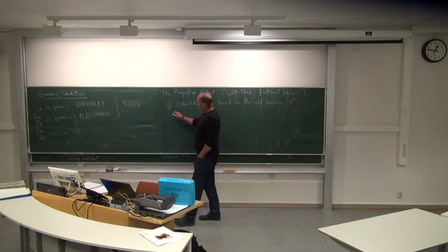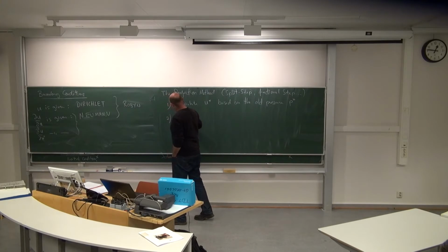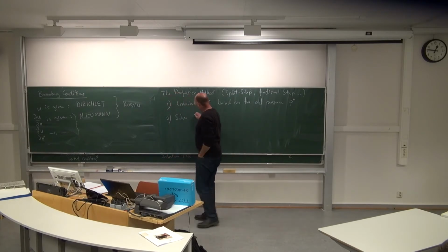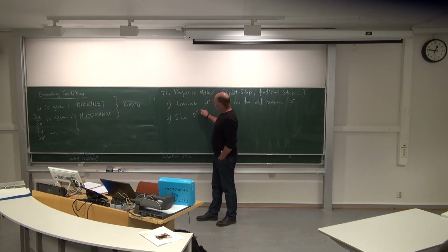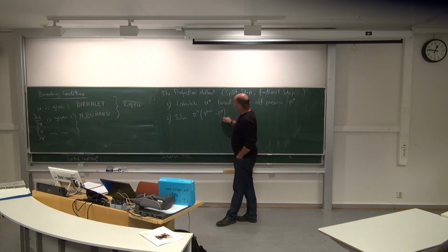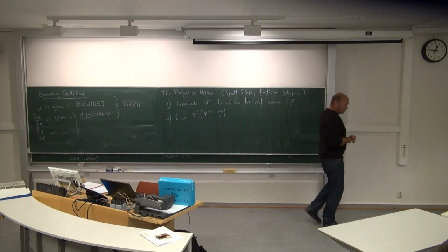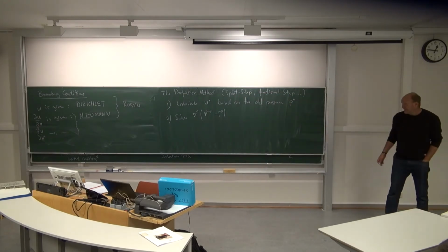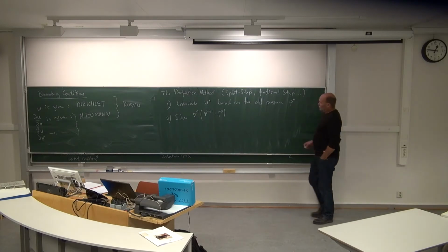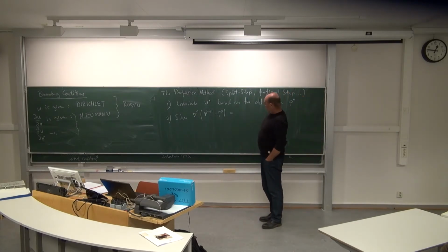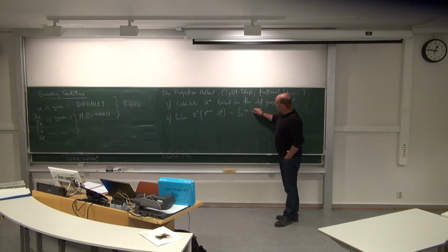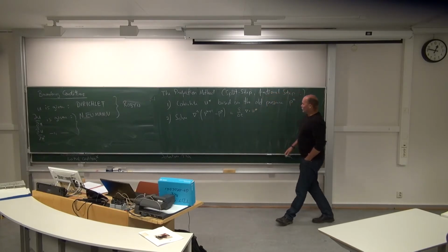Second step, that was a Poisson equation for the new pressure. Actually, the pressure difference between the new and the old pressure, and this one now should be equal to, do we recall here, what was it, rho over delta t, divergence of this tentative velocity field.